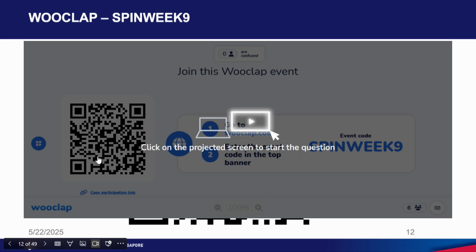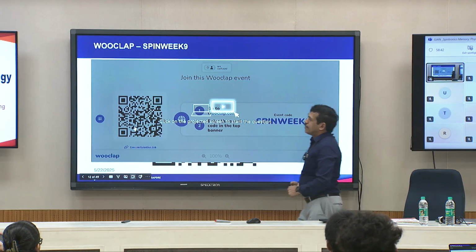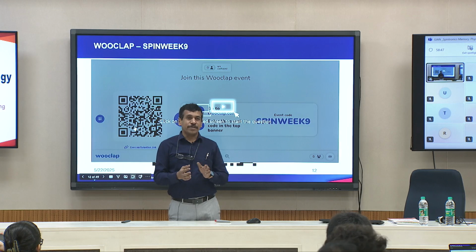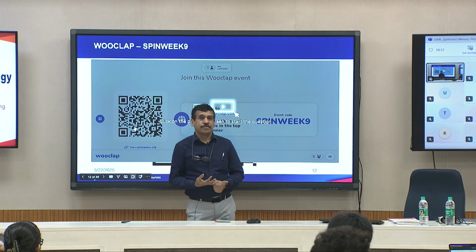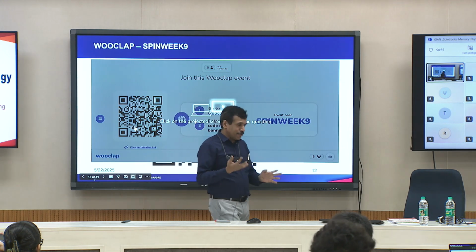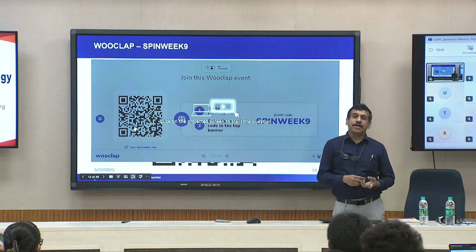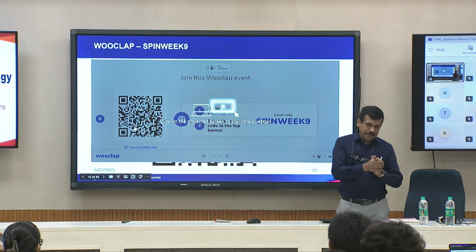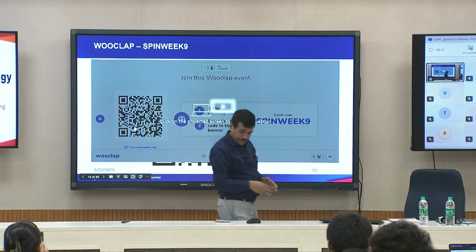Why do we use high temperature? We are operating MRAM devices at room temperature, so the pinning should happen at room temperature. Low temperature pinning is useless. So, we want to have pinning at room temperature or the operating temperature of MRAM, but we are annealing at high temperature to achieve the pinning effect. The annealing at high temperature is to ensure that you go above the anneal temperature.